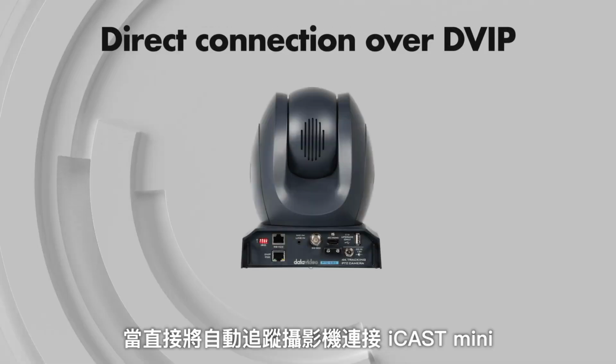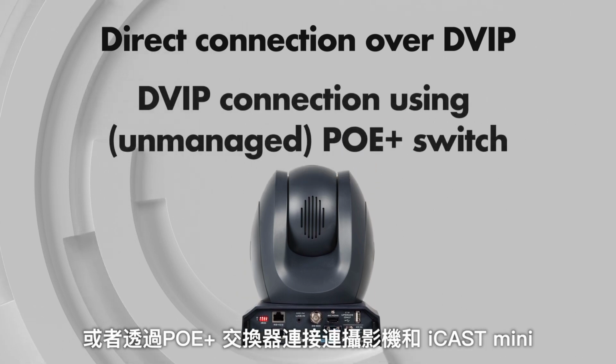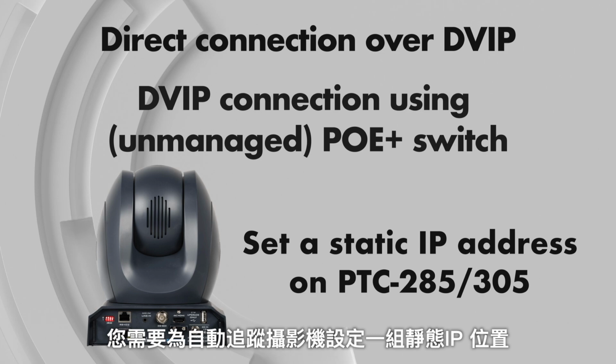When directly connecting your auto tracking PTZ camera to the iCAST Mini or connecting the PTZ camera to the iCAST Mini using a PoE plus switch in between, you're going to want to set a static IP address for your auto tracking PTZ camera. To do that, press the menu button and then scroll down to Network Settings.